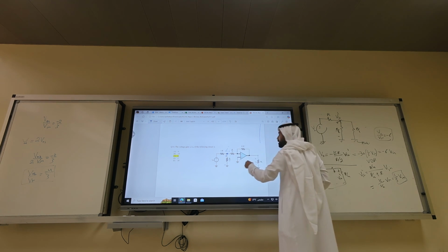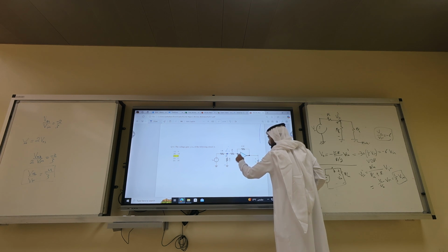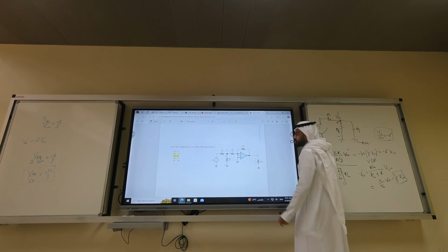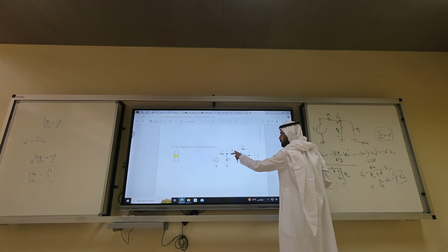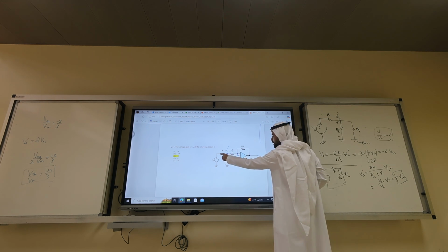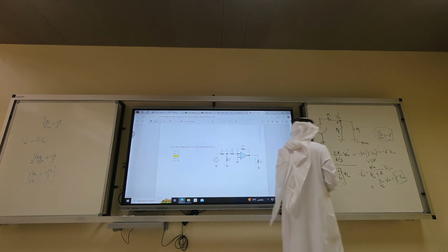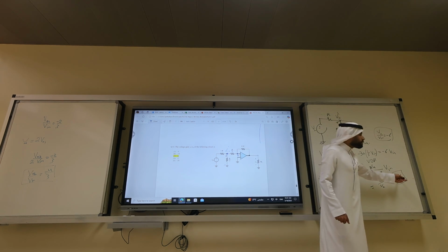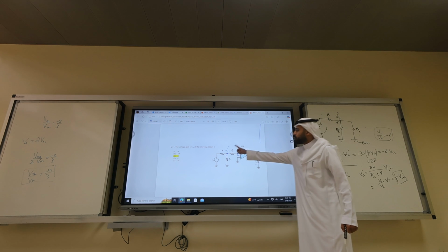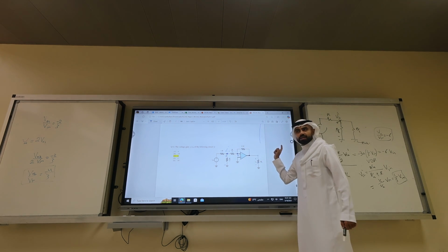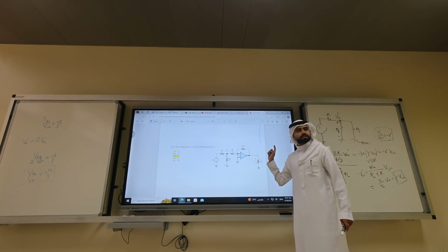And then I have to recognize that to get this voltage, I need to have virtual ground here. So the R over 2 are in parallel, in series with 1R. I can use VDR. Then I got V input prime, which is equal to 1 over 5 V input. 1 over 5 V input times minus 30 is minus 6.